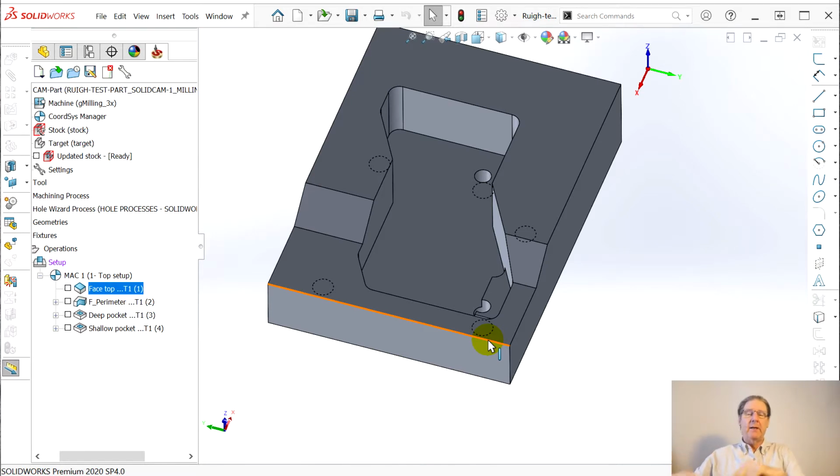If you go and change that, next time you open the CAM part, the PRZ file, Z for zip, then it'll prompt you to say, hey, the original file you made this thing from has changed. Do you want to update to that? And then it's pretty clever about, well, the stock's changed. It kind of highlights what you're going to have to go examine. I like that. It's a little more manual. It just doesn't go roaring through saying, oh, we're going to make new toolpaths based on what we think would be the new modified geometry. So that part I kind of like. But you got to get over this, what's it copying, what's it not. As always, I like to come up here.